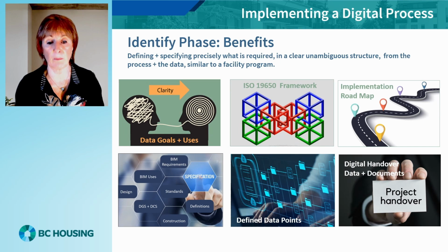Once identified, a BIM requirements document can be developed, including defining the required processes that the teams are to follow, for example, virtual coordination, and when the data is required to be present in the model dataset to drive downstream uses. ISO 19650 provides a great framework to build the BIM requirements around. The BIM requirements need to be specific as to the required outcomes, the specific data points required during the design and construction phases, as well as those required for the entire life cycle, and what processes are to be undertaken.